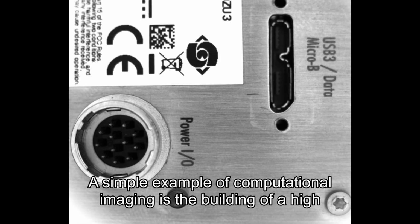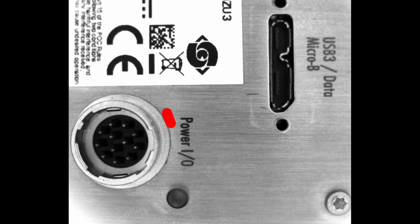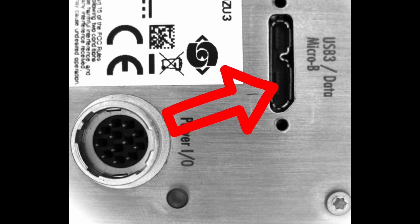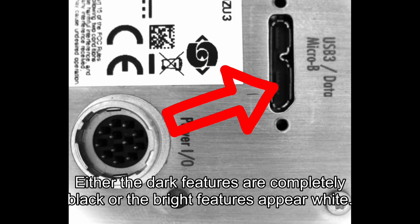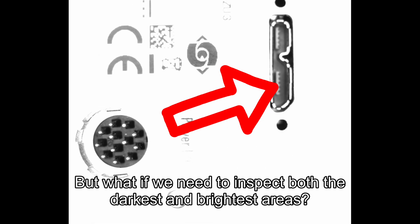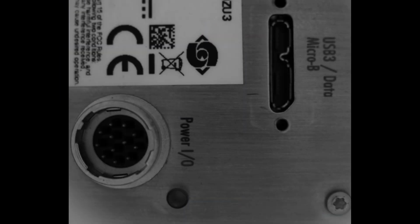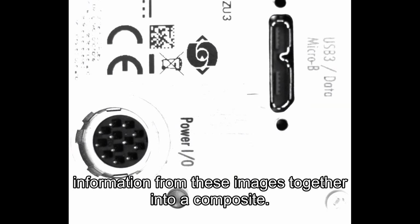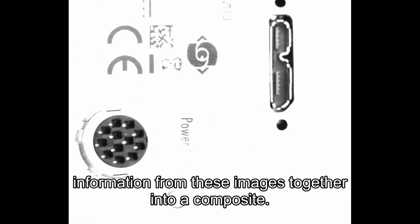A simple example of computational imaging is the building of a high dynamic range image. Cameras can have trouble capturing detail in both the darkest and brightest areas of an object. Either the dark features are completely black or the bright features appear white. But what if we need to inspect both the darkest and brightest areas? The solution is to capture images having different intensities, then combine information from these images together into a composite.